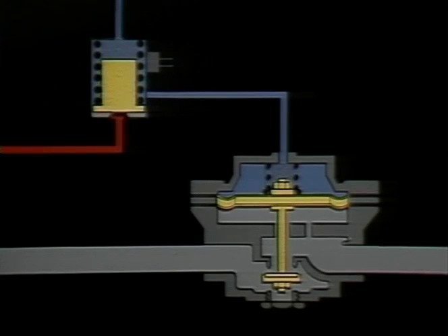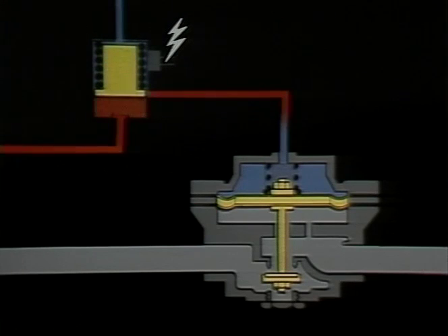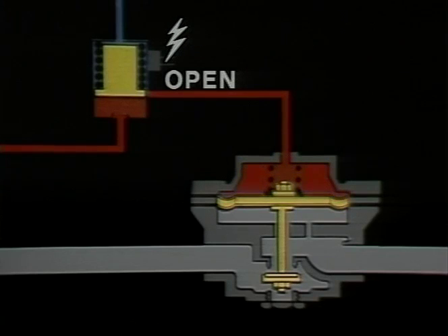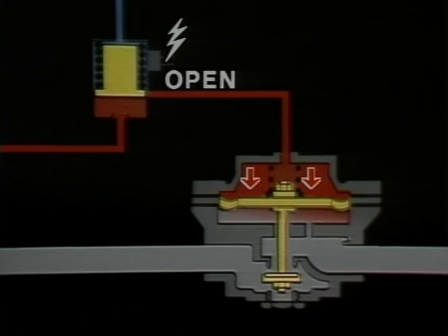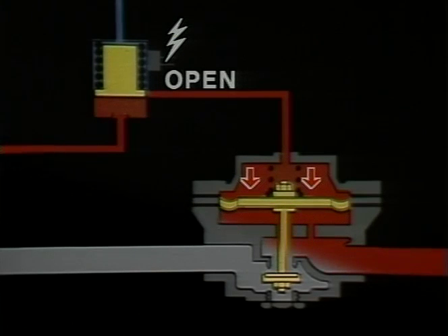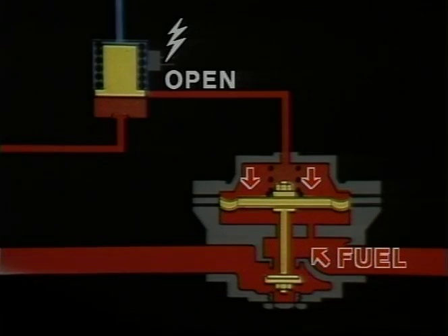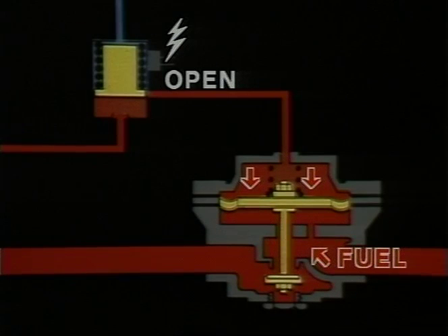At approximately 13% engine speed, the solenoid valve energizes and closes the vent port. The pressure port opens and applies pressure to the control side of the valve diaphragm. Spring pressure combined with pilot pressure holds the valve open during operation. Should the primary valve fail to close when the engine is shut down, the fail-safe function of the secondary valve goes into effect and the valve closes.